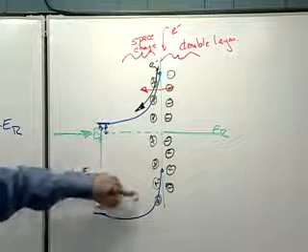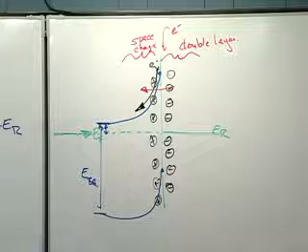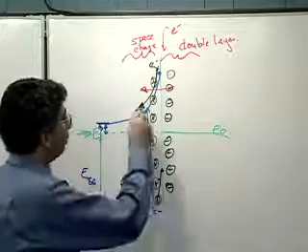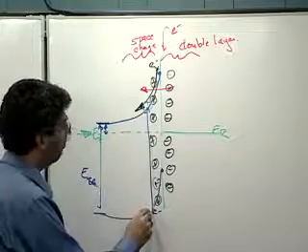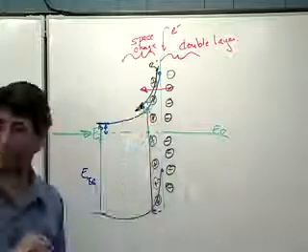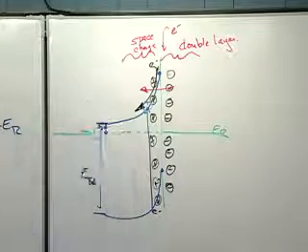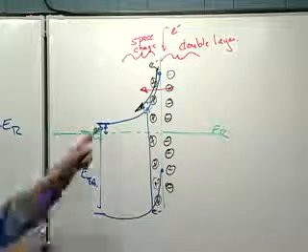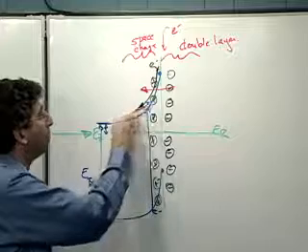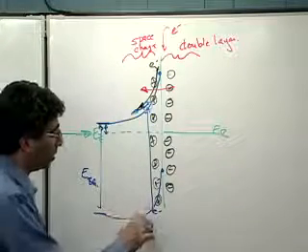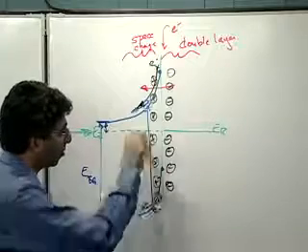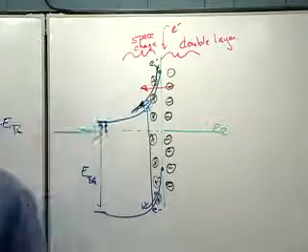Okay. If I now irradiate the surface with energy equal to or greater than the band gap transition, I will promote an electron from down here to up here, leaving a hole down here. And of course, an electron up here. If there's no band bending when that happens, then I just get rapid recombination. But if there is band bending, the electron feels the effect of the field and moves into the bulk of the semiconductor, and the hole also feels the effect of the field, as long as I do this near the surface where the band bending is, and it moves up to the surface.